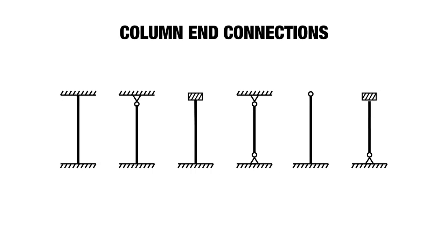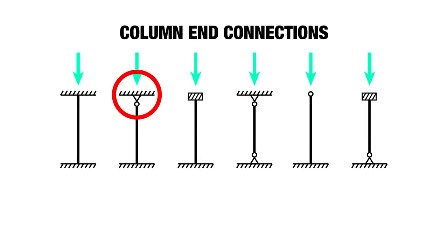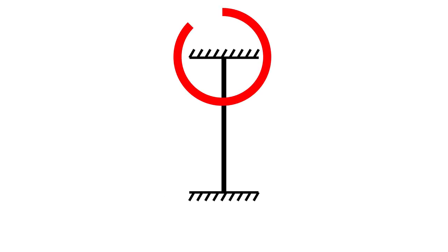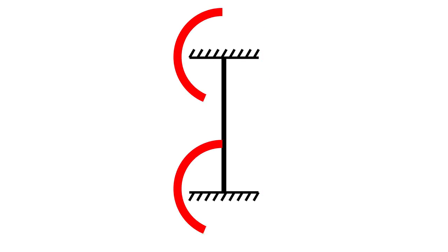So this is a little bit counterintuitive, but there are different ways to brace a column. And we have pin connections, we have moment connections, we have free connections, which are a little bit more unusual, and we have ones that are allowed to translate right to left, and we'll get to those. So if a column is going to buckle, we need to figure out not only the strength of the column and the length of the column, but the type of connection at the top and the bottom is going to kind of govern its likelihood of buckling.